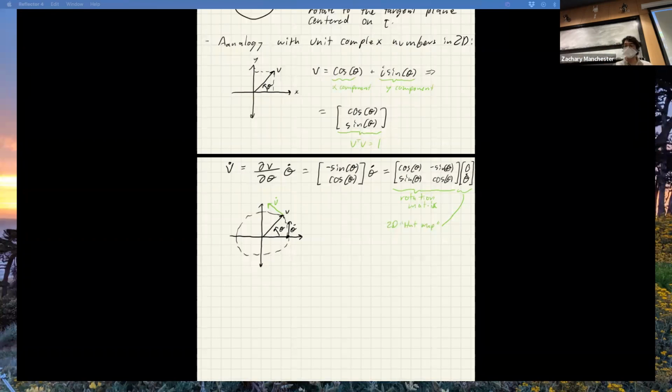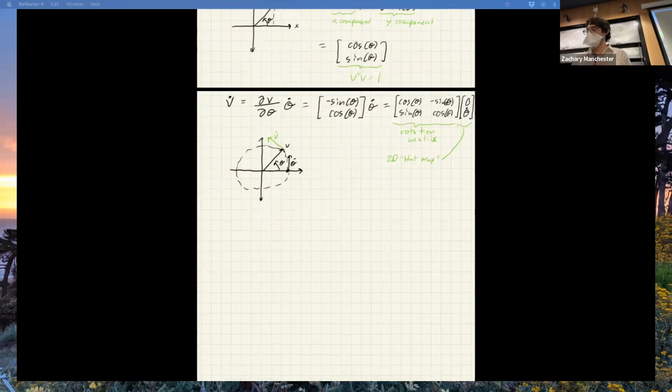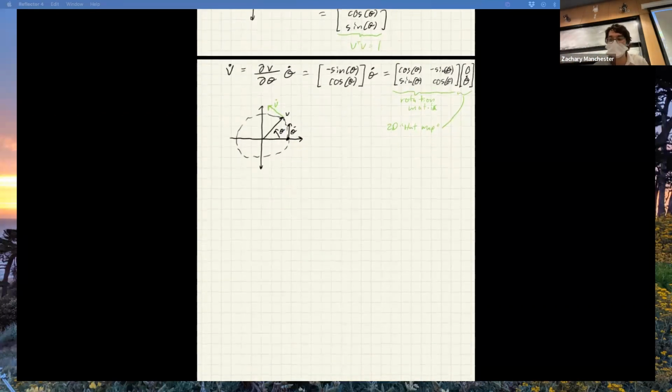Actually, this also gets at a bunch of the reasons why Euler angles are worse than quaternions in a bunch of ways. So here, one of the things you'll run into with using just an angle for planar rotation is that it has wraparound issues. And if you've ever tried to finite diff these things, there are ambiguities because it's actually modulo 2 pi and all this kind of stuff. And all that goes away if you write it using the 2D unit phasor instead of the angle. So there's a lot of similarities.